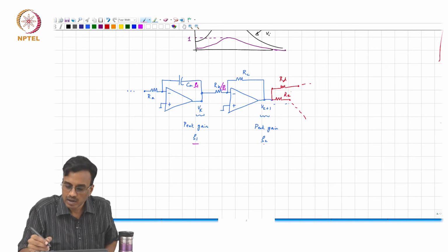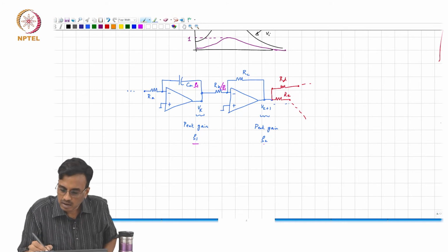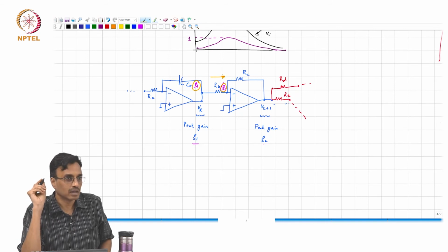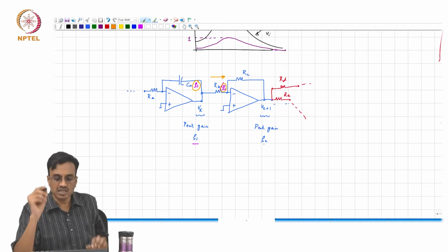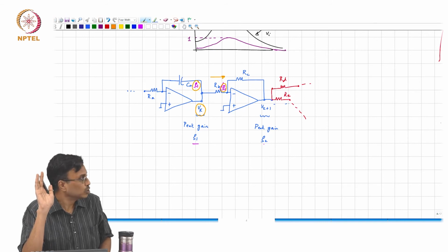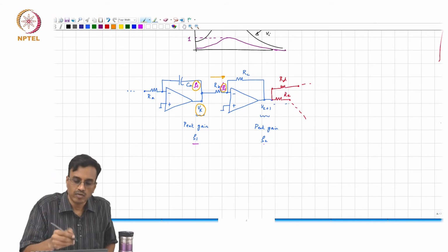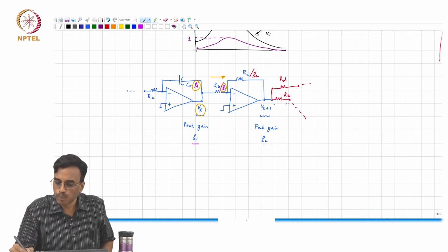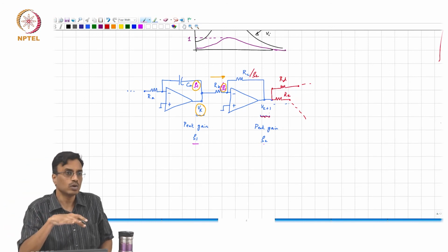Remember, multiplying this by G1 and dividing this by G1 has not changed the current that's flowing through that resistor, correct? All that it has changed is the peak gain there, right? So what do we need to do? We just need to change RC to RC times G2, right? That will push the peak gain at Vk plus 1 down to 1.